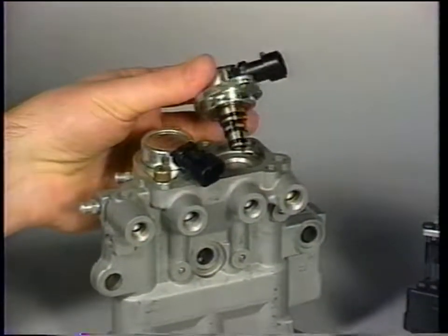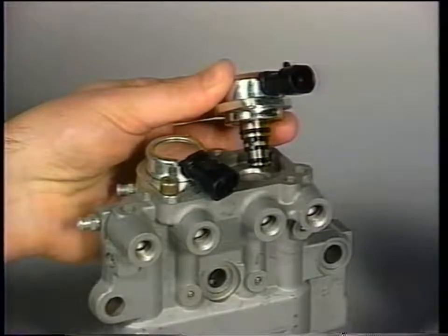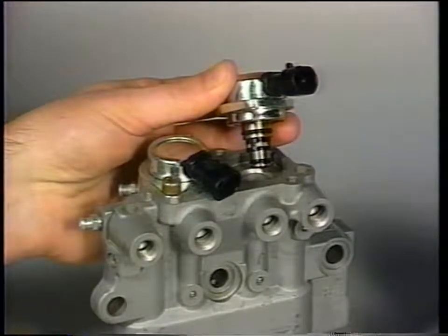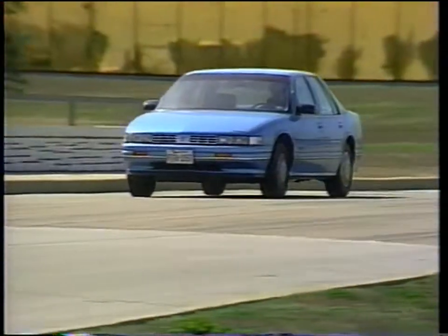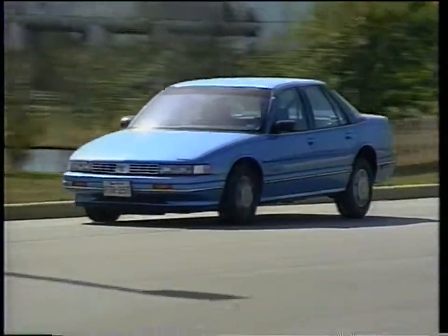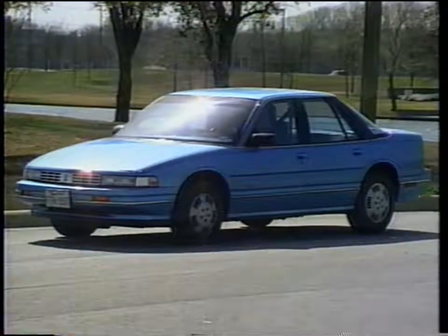The modulator contains 2 isolation solenoid valves to block off the front brake circuits when anti-lock braking is required. But there's no isolation solenoid valve for the rear brakes. One isn't needed because the rear brakes on front-wheel drive vehicles do very little work anyway, handling only about 20% of the vehicle's braking effort.